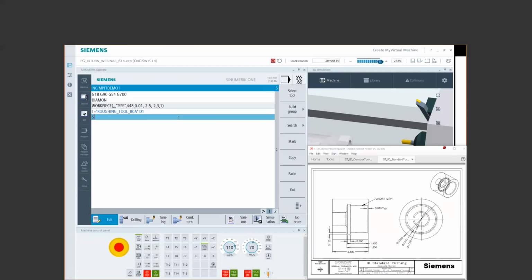Give me some RPM. So let's do a little bit of straight RPM work. I'll just throw my spindle up at 2000. I do want to turn on my spindle, so that would be like an M3. Maybe turn on some flood with an M8. Probably going to want to make sure the machine is in G95, or feed per rev mode. So G95, F, and then give it some feed rate, right? So this is pretty standard for the G-code side.